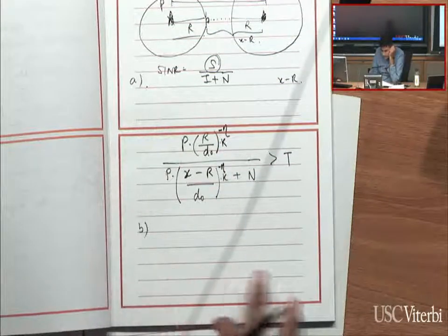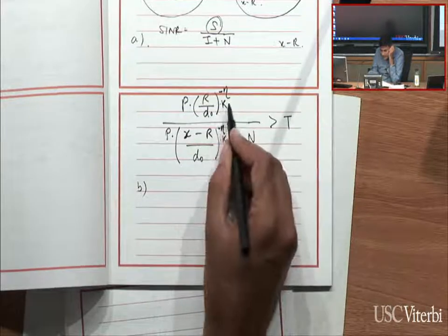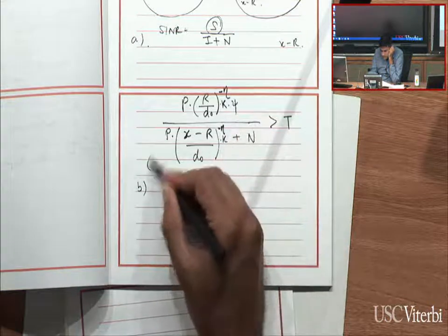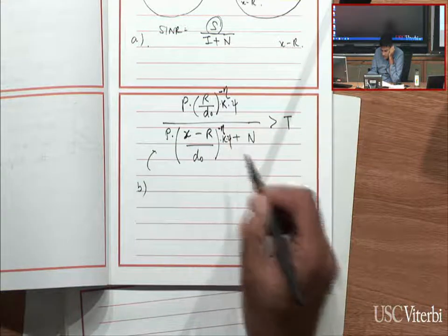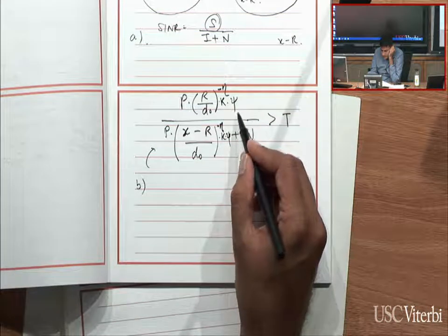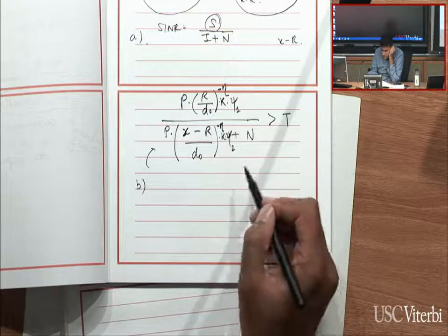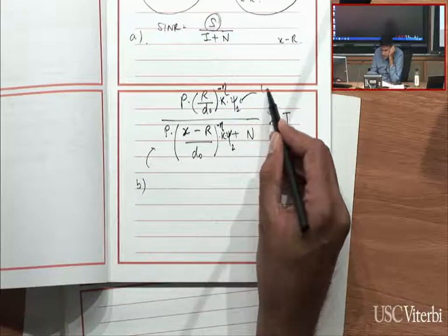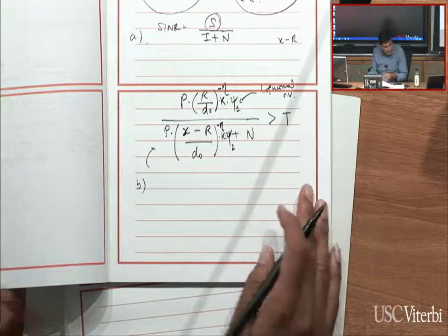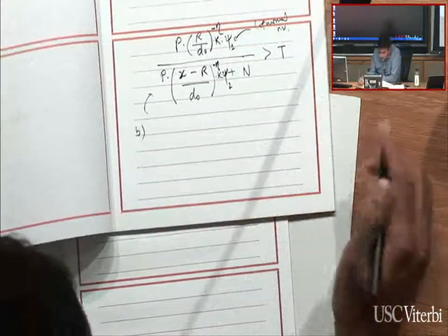For part B, the key difference is that it's not just this, but we're adding to it, let's call it, random variables. They're both different random variables, one for the signal, one for the interference, and these are your log normal random variables. And for this, I certainly did suggest to neglect the noise power and just focus on signal to interference plus noise.